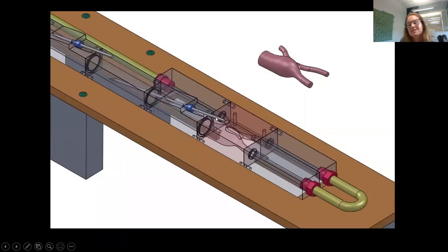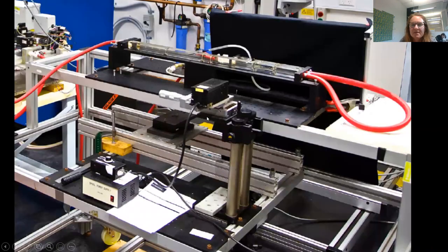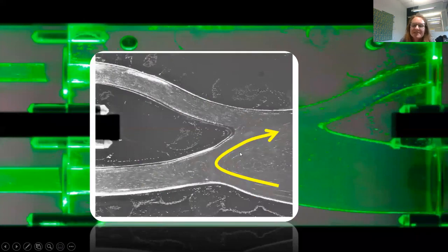So then we built a double scale fistula flow rig with double scaled needles, which actually have quite a complex geometry at the tip. We hadn't realized until we asked our workshop to make them. So we built a double scale rig so that we could understand exactly what was happening. This is the rig set up in our lab with some flow visualization laser happening. So we were able to then see what we had imagined was happening and what we'd seen in some of our CFD results, with the flow very sharply going around the corner and not much happening in these distal vessels.